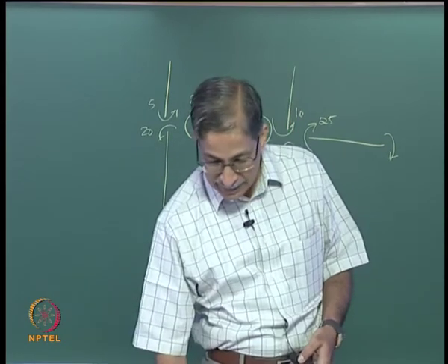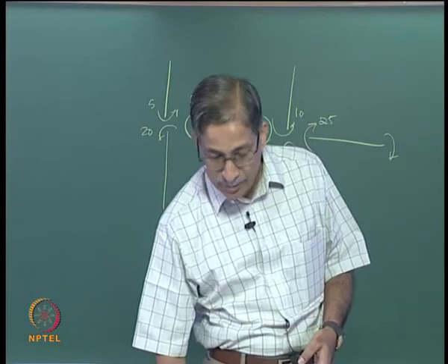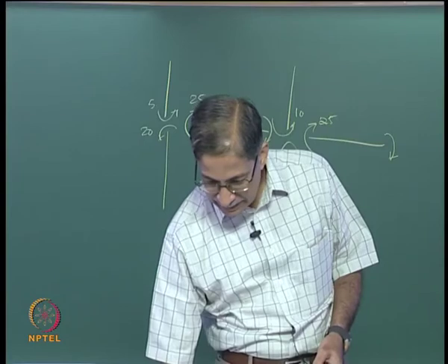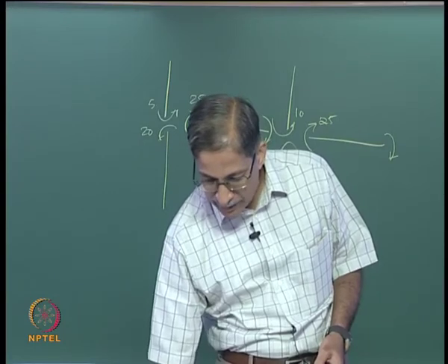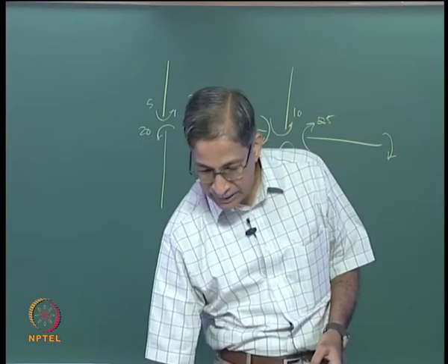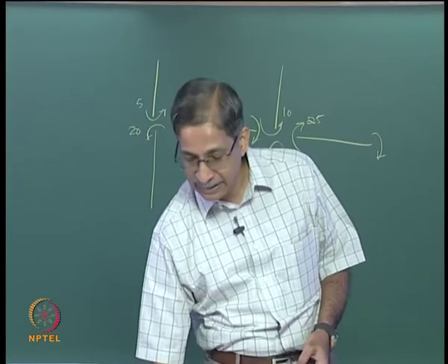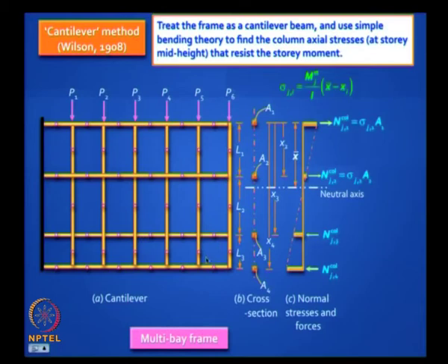You are cutting the section at any story, so we need to talk about a story moment. See, do you agree? If I cut a section here, the bending moment in the beam is P6 into half this distance. Do you agree? So that is my story moment here. Like we had story shear, we can talk of story moment.